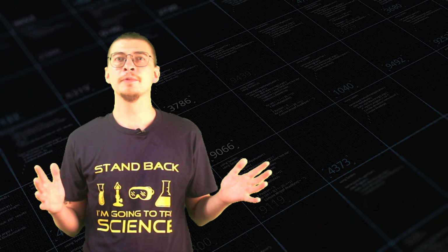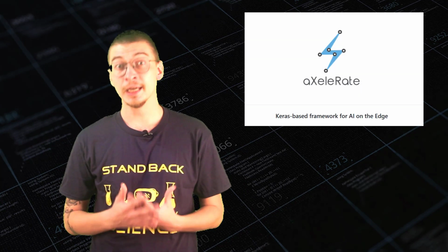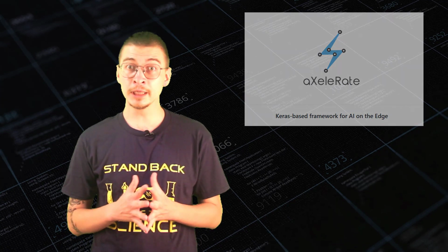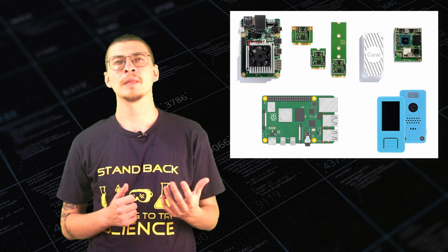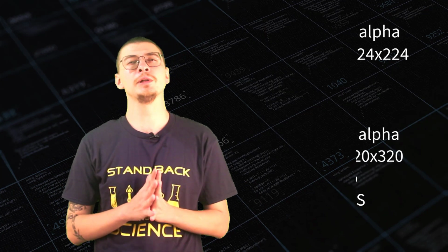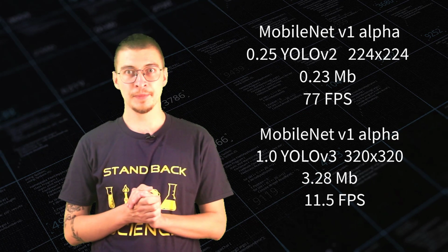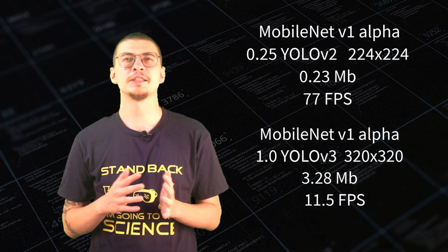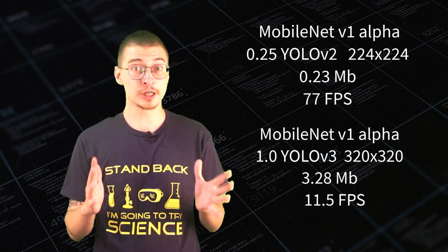For further reading, have a look at the TensorFlow Lite documentation and the convert.py script of Accelerate, my personal project that simplifies training of common computer vision networks for inference on embedded devices. So here are benchmark results for the 2 baseline models with TensorFlow Lite integer 8 inference. As you can see, we have a noticeable speedup, especially for larger models.